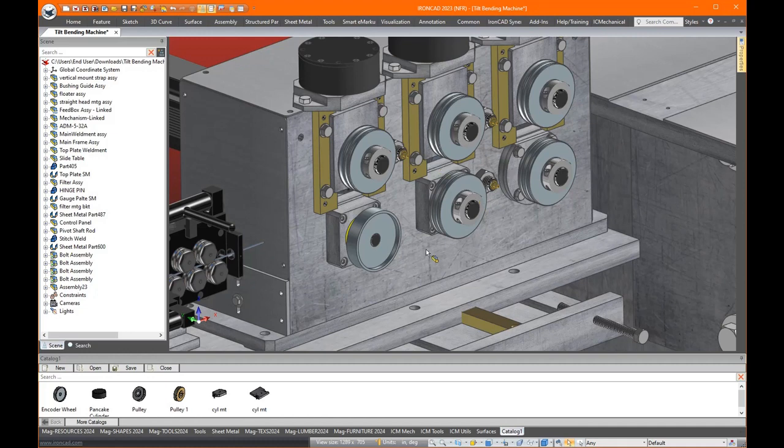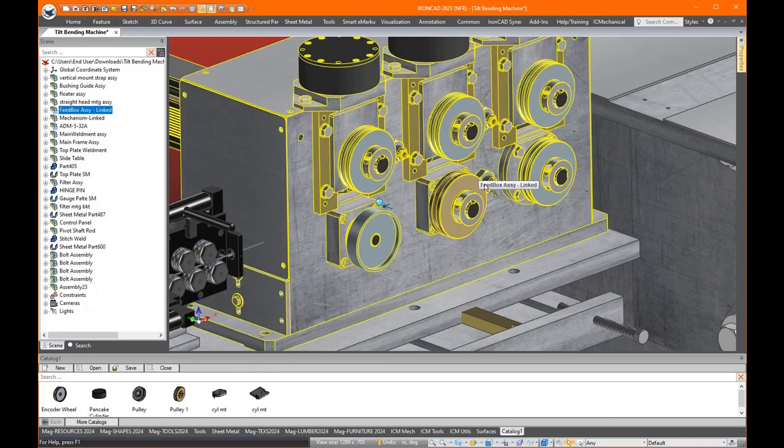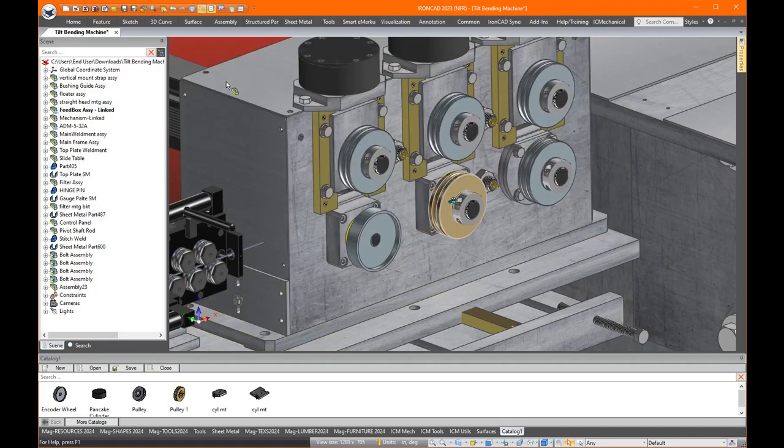So the process for replacing a part is simply highlighting the part and then coming into your catalog and finding the one you want to replace it with. In this case, I want to replace it with this one. Just hold the control key. That's it. Holding the control key, you drag right onto that part, and it replaces the part within that assembly. Okay, because we selected that part first.